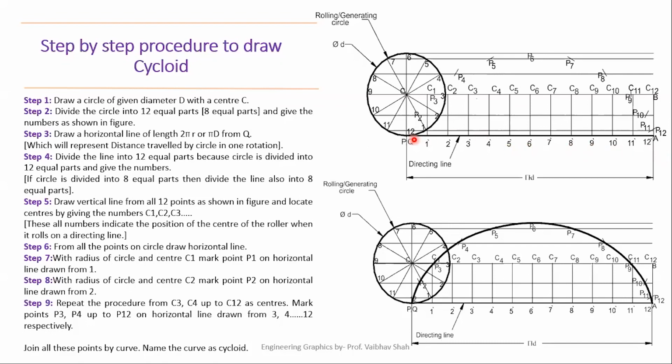Now, after drawing these points, we'll draw one horizontal line parallel to this tangent line from this center point C, which is also known as a center line. So let us draw one horizontal line from the center point C of exactly equal length of your tangent line passing from your point P. So we have drawn a parallel line. For drawing this line, you have to simply use your roller scale or your drafter edge.